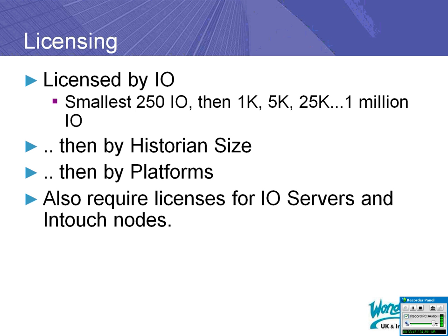It doesn't have all the functionality of standalone InTouch. For example, it doesn't log its own data because that's done by the historian. It doesn't use the InTouch security model because that's done by System Platform. And it doesn't generate alarms because again that's done by System Platform. So InTouch for System Platform is a cut-down version of InTouch, and it's also cheaper than a standalone InTouch.